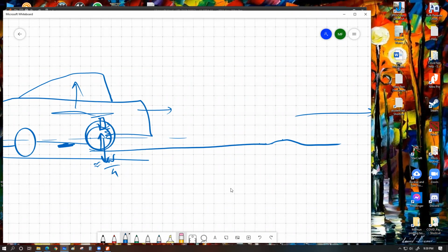If you don't allow the shock absorber that amount of release time, then it is just going to behave like a solid rigid object. It's not going to be able to absorb the energy and release it over a duration, which is the purpose of a shock absorber. So if you have a fully bumpy road, then you're definitely going to feel all the bumps. There is one type of suspension called electromagnetic suspension, which can actually avoid that, but I'm not getting into that.